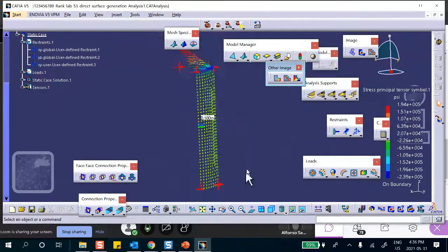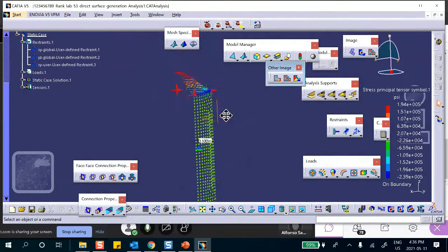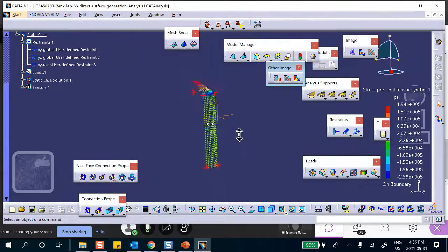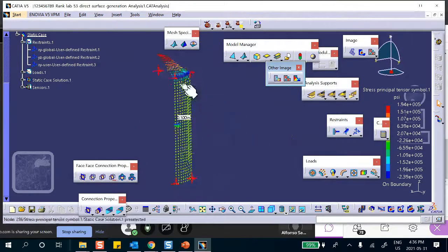Then you have to do a good mesh in places which are problematic. You cannot use only shell elements. The rest of the structure you can do shell. Close to those openings, close to these seams, you have to do solid elements. And this is something that will take time. You cannot sit and do it in the 15 minutes that I'm doing. It takes time. This PR over T is valid for just the cylinder. Forget about the ends. Very long cylinder. But if you have holes, all bets are off. There are no formulas like that anymore.